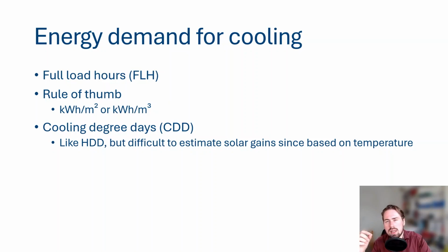The problem here is that it's a little bit more vague or complicated than the heating degree days, because for heating, the heat losses are due to the difference between the internal and the outside temperatures. But for cooling, most of the cooling demand is actually coming from solar gains. So it's not that trivial to just correlate the outside temperature with the cooling demand of the building. Therefore, if you really want to calculate the energy demand for cooling, there is also software for that, or you can use a certain building standard for that as well.